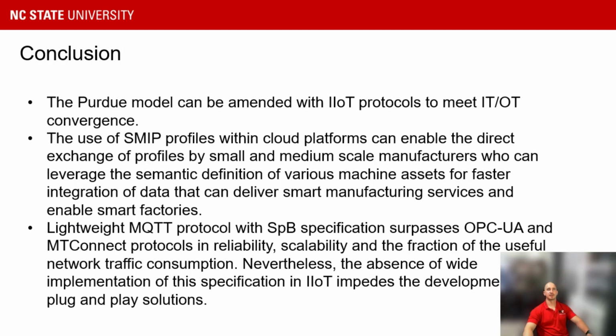This work demonstrates how the MQTT Sparkplug B works with HAAS CNC machines. Work is still required to translate machine-specific codes to gather data and have it transported to the subscriber endpoint. This means an information model is required to enable interoperability between various device assets and machine vendors. While information models like MTConnect exist for CNC machines, not all machine types and their associated assets have means to standardize information coding to enable interoperability.